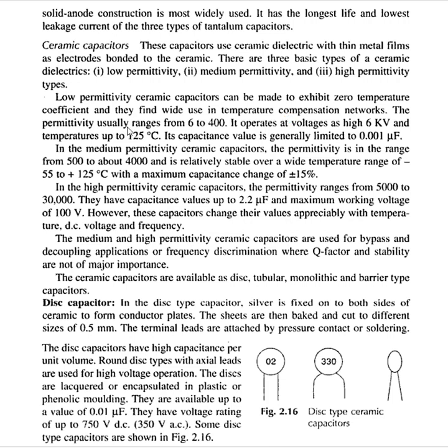The permittivity usually ranges from 6 to 400. It operates at voltage as high as 6 kilovolt and temperature up to 125 degrees Celsius. Its capacitance value is generally limited to 0.001 microfarad.